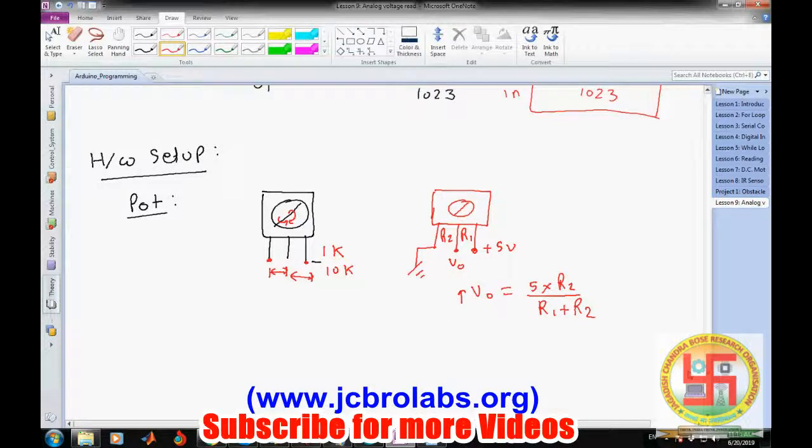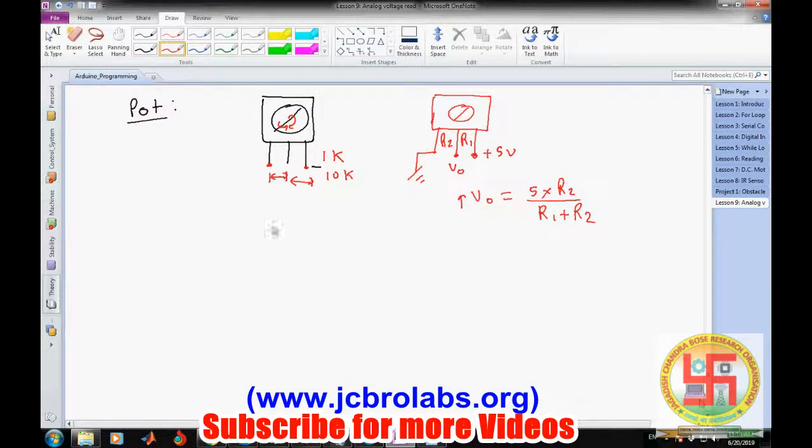We have connected this particular port to our Arduino, and the connections are very easy. One point is connected to plus 5 volt VCC and the other pin is connected to ground, and this particular pin at which we are getting the varied voltage is connected to the A0 pin of the Arduino. So this is Arduino.